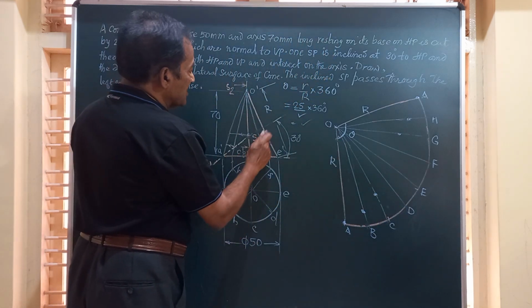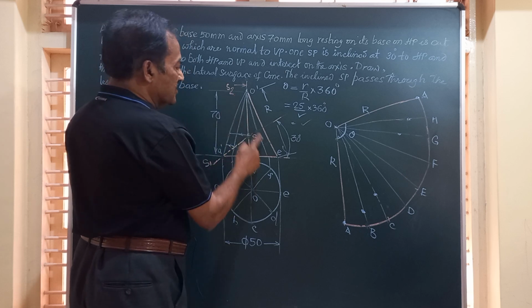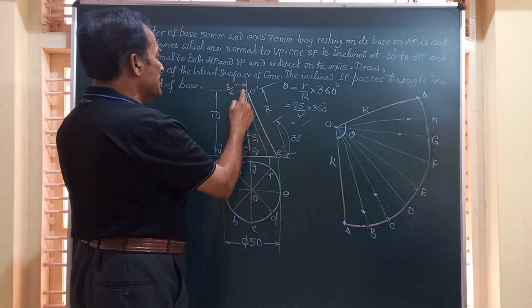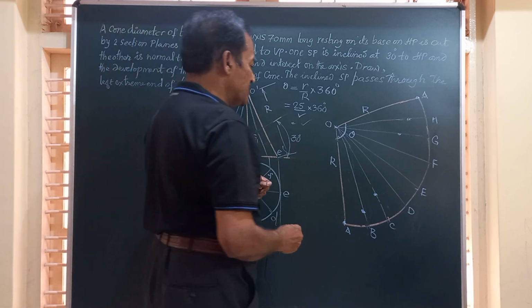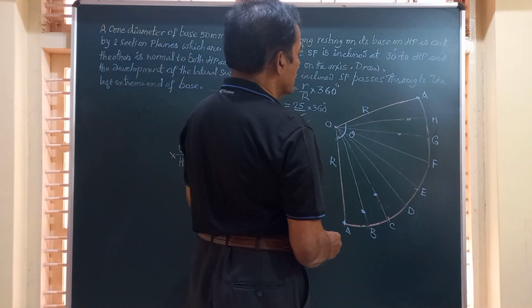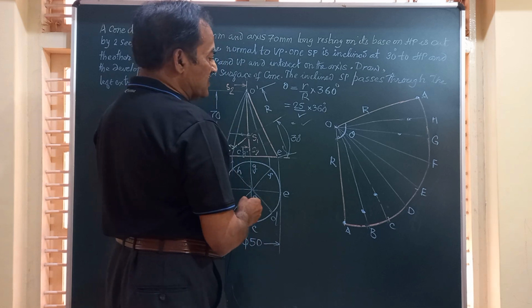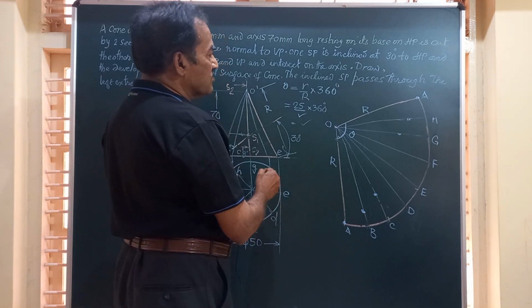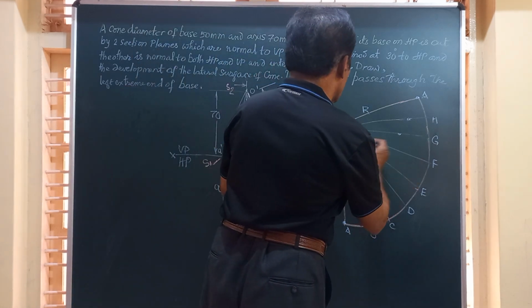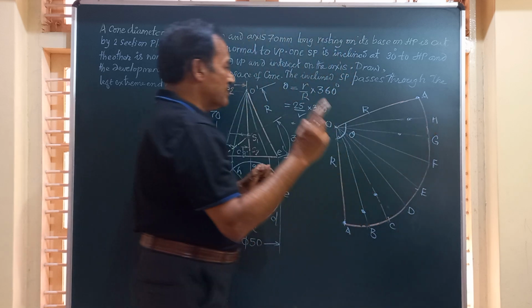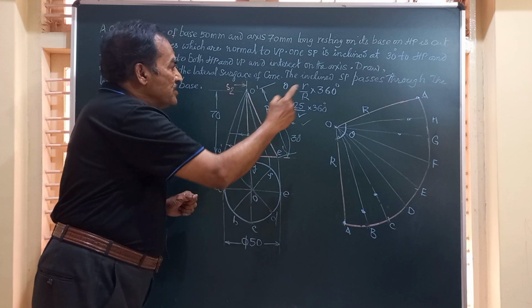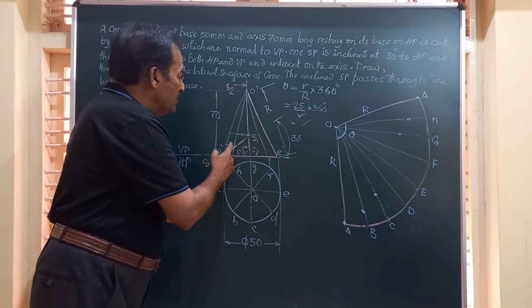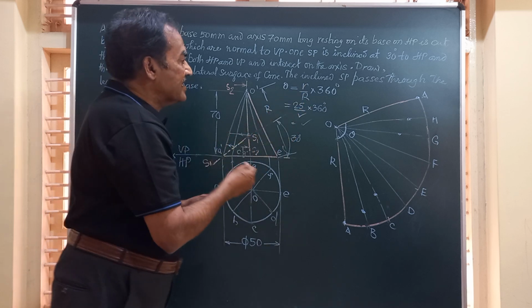Then these two lines we have marked, and this is cutting up to the center. So friends, we have to join all these points so obtained by a smooth continuous curve, and this part is to be retained. So friends, you can observe a very important thing here, that this portion is going to be a straight line in the development, whereas this is going to be a curve.